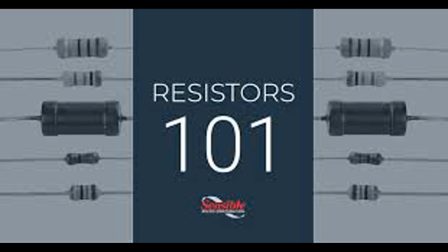Quarter-wave transformer. Description: A quarter-wave transformer is a transmission line with a specific length and characteristic impedance. When the length of the transmission line is 1/4 of the wavelength of the signal, it can match impedances between the source and load. Example: In microwave circuits, quarter-wave transformers are often used to match the impedance of different sections of a transmission line.